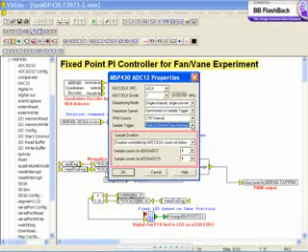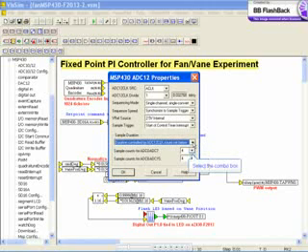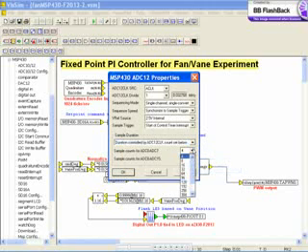Here you can set your sample duration. To get predictable results without an external trigger, we recommend using the ADC clock. You can then select the sample duration for each channel bank by selecting the number of sample counts. Press OK here to return to the main session.